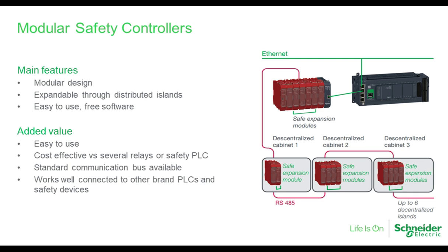So as shown here, we have a PLC, and in the picture it's gray, and then you have a safety controller, which are the red portions. They're both programmable. The PLC, or the programmable logic controller, its primary job is to run the process, run the machinery. The safety controller, its only job is to manage the safety.